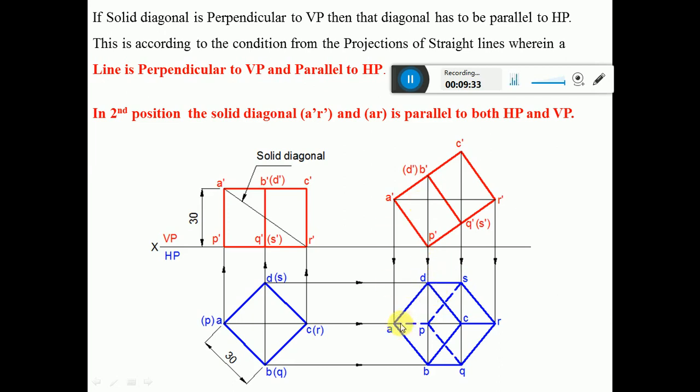So all the exterior edges of the boundaries of the solids are visible. So join between A to B, B to Q, Q to R, R to S, D to S and D to A. This is going to form all the exterior edges of the boundaries of the solid. So you dark them. When you look from the top view, ABCD is near to the observer. So join between D to C and C to B, that is going to become visible.